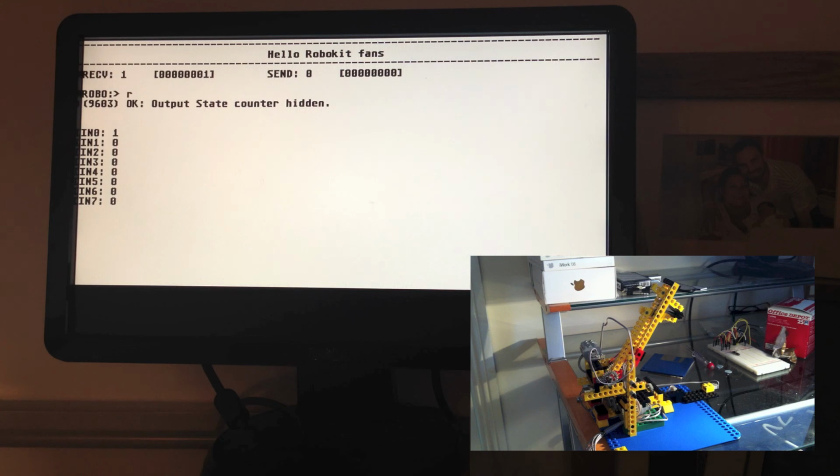I can even drive, for example, the number of clicks between the timer service. So by default it's set to 10, but I can set the poll interval to be much later. It's measured in number of ticks, so it's how many times the timer B that it's associated with. It directly controls how many processor ticks before that piece of code is run. 10 works quite well on an STE. So as you can see, I've got very deep control at runtime on all of this stuff.